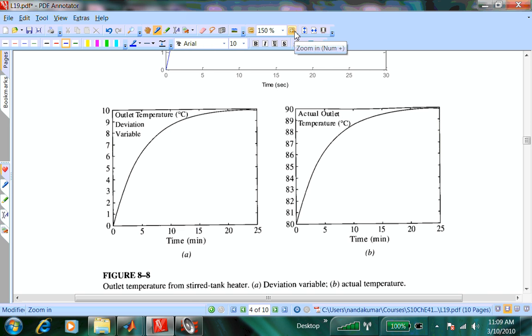It's T prime. The right-hand side is the actual sheet from 80 to 90 degrees. The outlet temperature for the original steady state, when we were putting 265 kilowatts or whatever, was at 80, and it goes to 90 degrees by this increase in the inlet temperature. The heating rate is the same. So analytically, question?